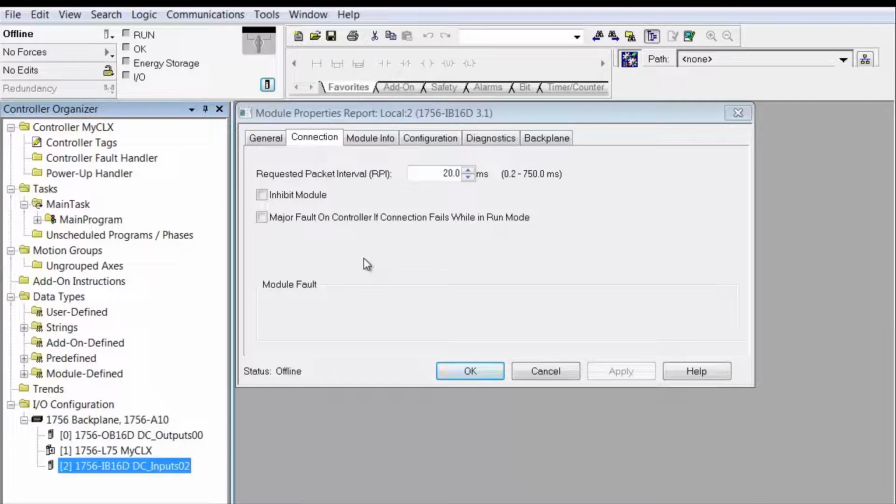In this case, when the system boots up, I'm going to paraphrase a little bit. It goes out and looks at its hardware configuration over here. That's what we're creating, a virtual hardware structure. It looks and goes, oh, I've got an OB16D in slot 0. It goes to slot 0 and says, hey, slot 0. Now remember, slot 0 is an address, a physical location on the backplane that the processor can communicate with. Not activate, but communicate with.